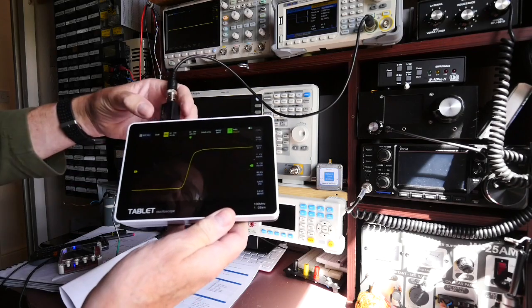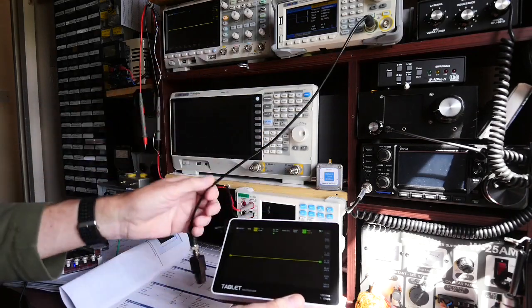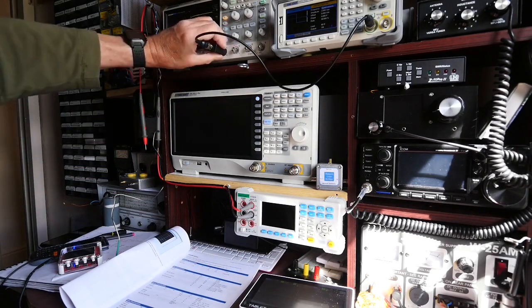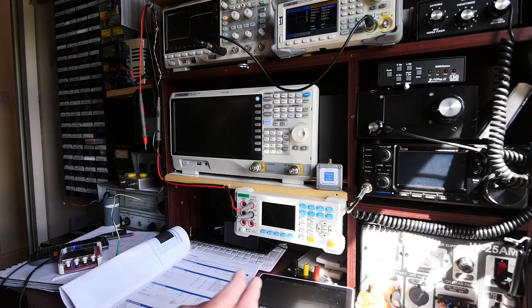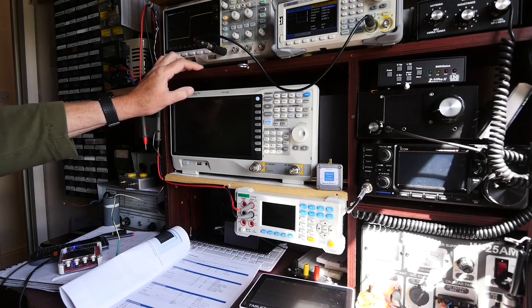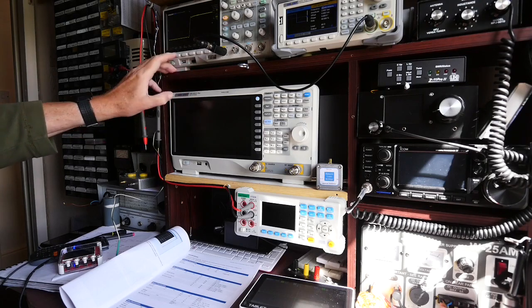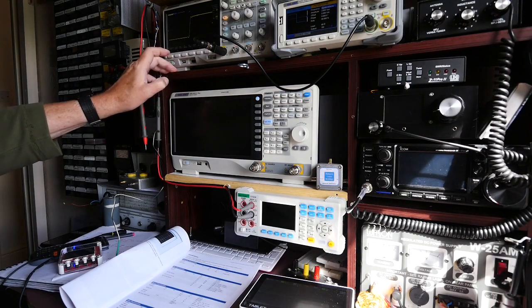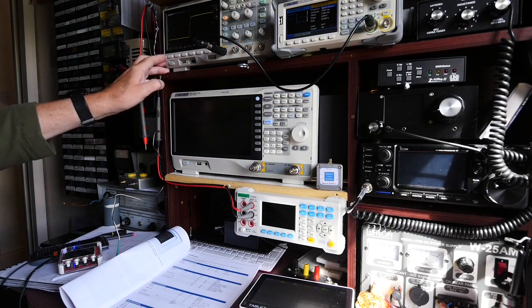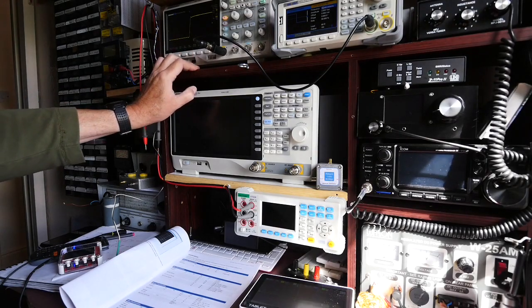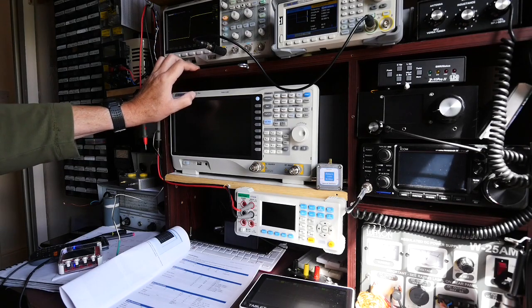So that's what we do the maths on, to do the calculation, which we'll look at on a table in a few minutes. Now I'm just going to disconnect that and pop it onto my Siglent 1104X, which I've also got set at 10 nanoseconds per division. And the nice thing about the Siglent, of course, is it will actually measure rise time for you using that 10 to 90% method. So I'm going to just clear the statistics. So it's now measuring the rise time.